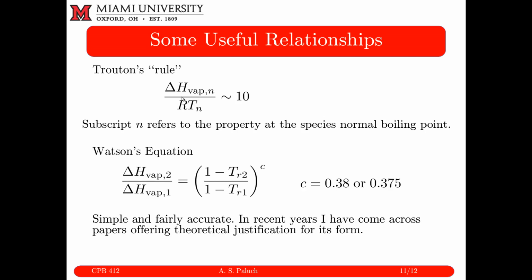Okay. Another very common or very powerful technique is Watson's equation. I've actually seen some physical justification for Watson's equation. What we have here is the ratio of enthalpy of vaporization at two different conditions. And so remember, enthalpy of vaporization corresponds to vapor-liquid coexistence. So if I say this is at some T2 and that's at some T1, remember, the pressures are different too, right? But they're dictated by that temperature.